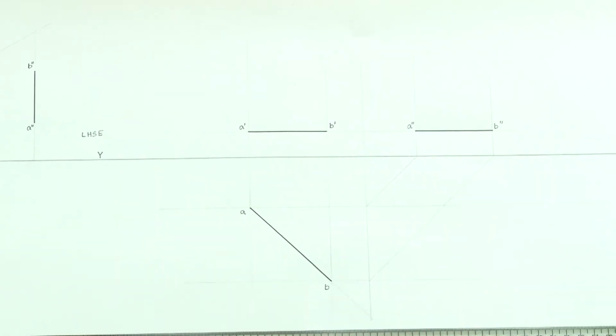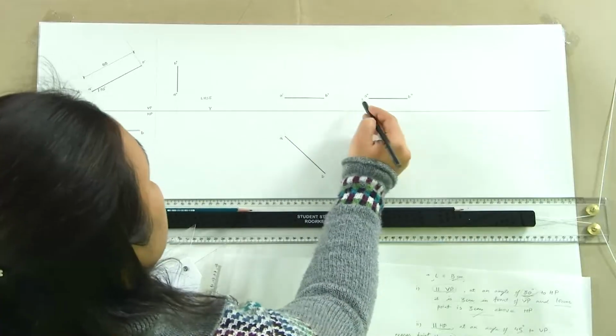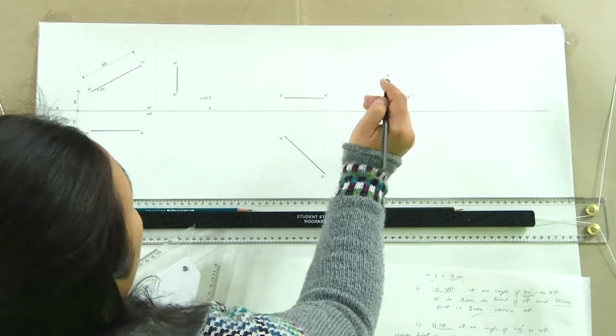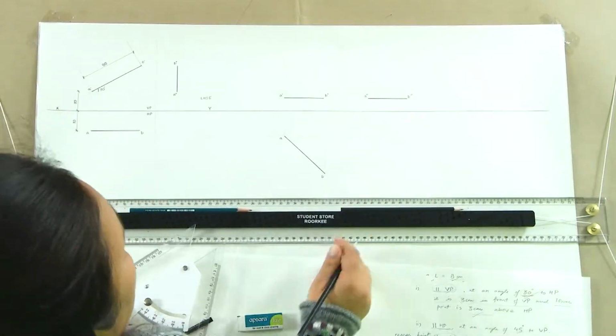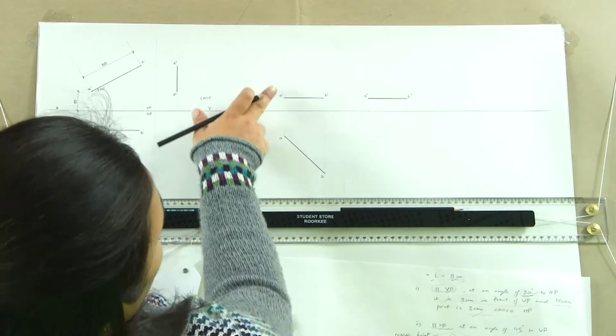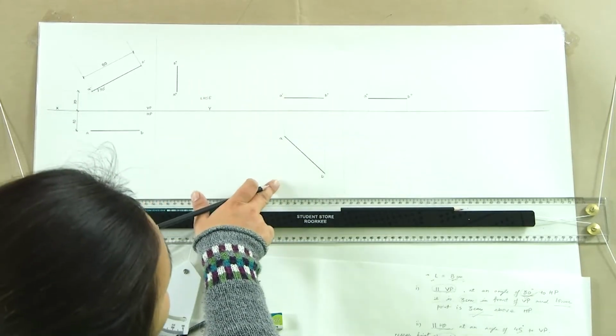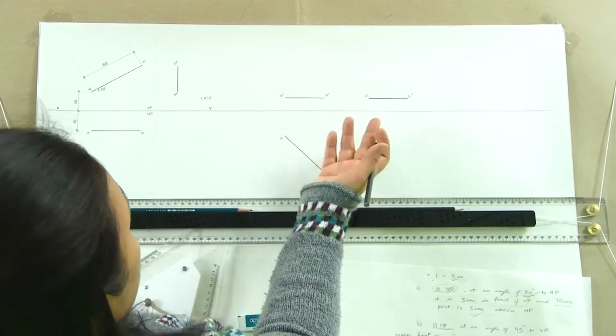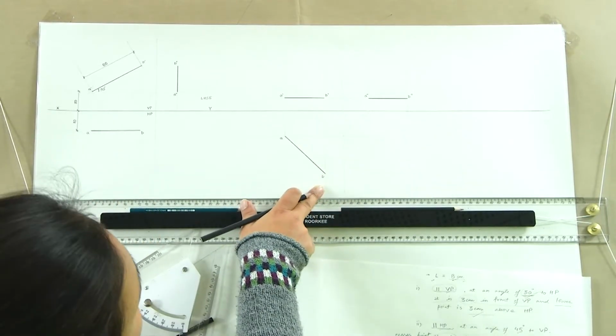Now, this is absolutely scientific because what we are seeing here is totally unambiguous. The projection of A in plan will always meet up with projection of A in the elevation to result in the side elevation. There is no ambiguity about it. In vertical also we can see that the projection of A will not result in a point B. The projection of B will not result in a point A. So, that is how we will always draw: unambiguous, very clear, and it is a standard format in which we are going to be doing things.